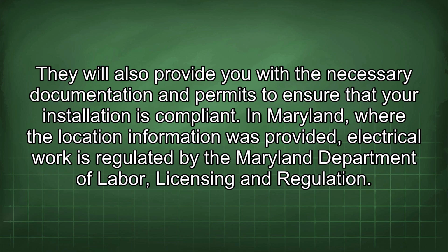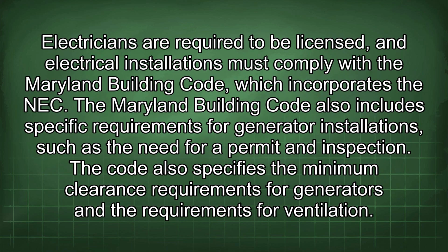In Maryland, where the location information was provided, electrical work is regulated by the Maryland Department of Labor, Licensing and Regulation. Electricians are required to be licensed, and electrical installations must comply with the Maryland Building Code, which incorporates the NEC. The Maryland Building Code also includes specific requirements for generator installations, such as the need for a permit and inspection. The code also specifies the minimum clearance requirements for generators and the requirements for ventilation.